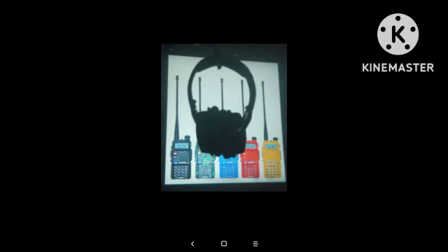Number 56. You have connected your handheld VHF transceiver to an outside gain antenna. You now hear a mixture of signals together with different modulation on your desired frequency. What is the nature of this modulation? Receiver intermodulation interference.